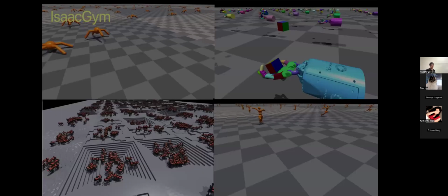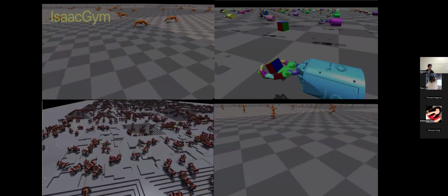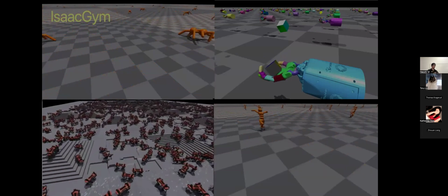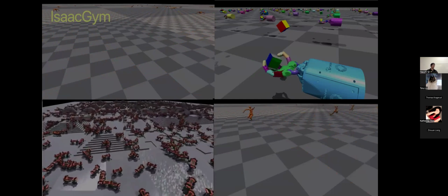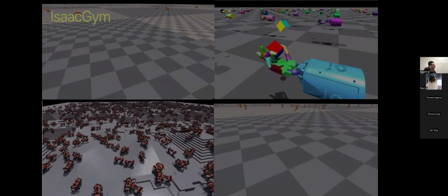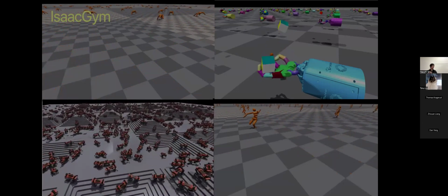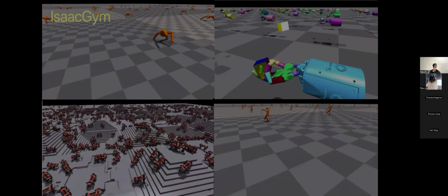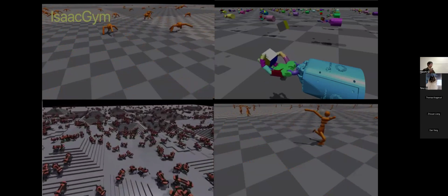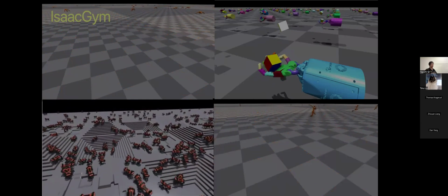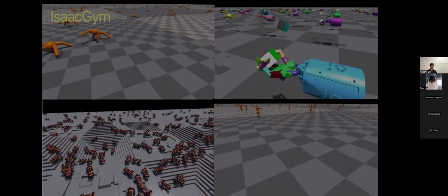And of course, there are problems with using Isaac Gym, mainly coming from the fact that you are using the GPU to solve all these contact detections and collisions. One thing that maybe was not considered before, at least for me, is that in deep learning we always use floating point arithmetic. Empirically, it's already enough to train good neural networks using 32-bit floating point.